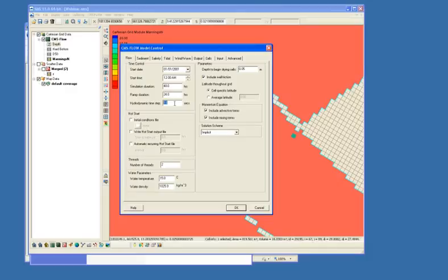So if you have areas that are having a lot of wetting and drying, you need to make sure that you're able to represent those so that they don't all dry at one time in one time step, just to get the hydrodynamics correct. And so it doesn't make any sense to run an implicit solution scheme with 1 second time steps. That would take a really long time.